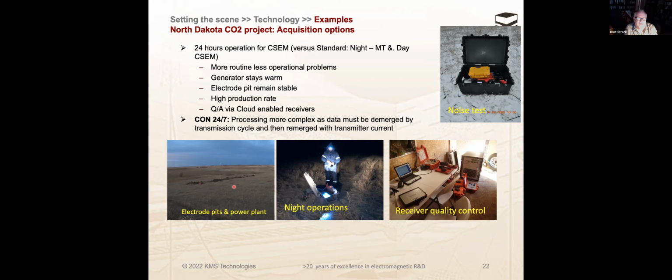So it's always good to have more electrodes in order to make the plants more stable. In Asia, we could actually see on the transmitter, and they were trying to do the electrodes on the cheap side. And we could actually see when one of the electrode plates burned out and the current dropped so quickly that the current stabilization, the transmitter is current controlled, couldn't catch up. So boom, all of a sudden you had some 10 amp drop or something.